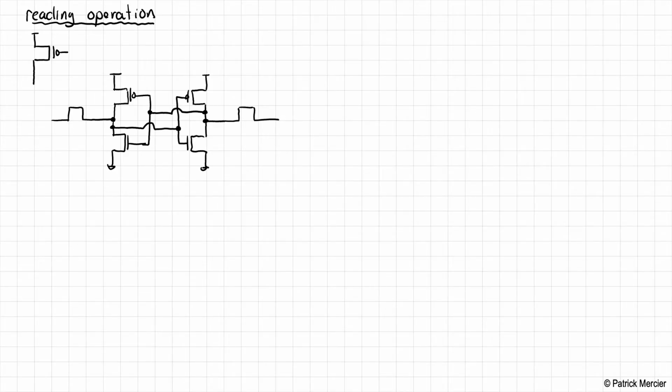Okay, so this is a diagram of this back-to-back inverter structure. So this is our entire SRAM cell here. And I've compressed things a little bit more vertically than I would have liked ideally here, but hopefully this will still work out. Okay, so it turns out we have a word line that comes into the circuit, goes all the way through the circuit, and we connect our access transistors to this word line.